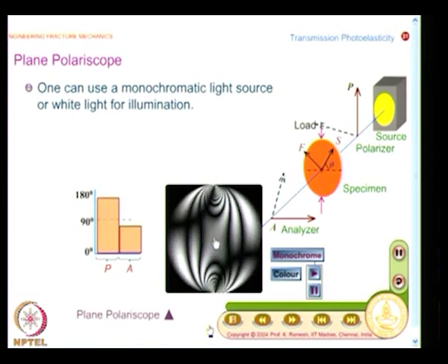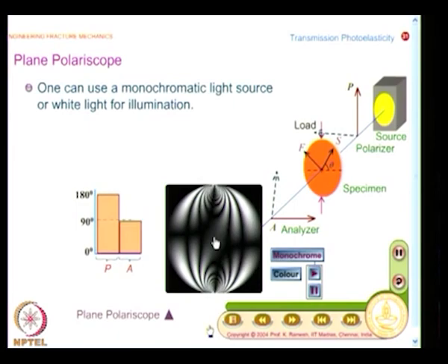The model cannot distinguish whether the phase difference is 0, 2 pi, 4 pi, 6 pi, or 8 pi, it cannot differentiate that. So, that is why I get multiple contours. So, one possibility of fringe formation is the model behaves like a wave plate, so the input plane polarized light comes out as plane polarized light unaltered.